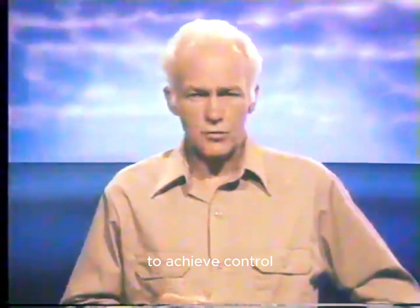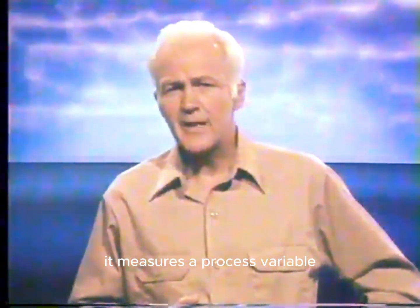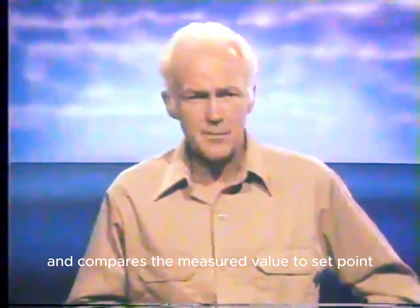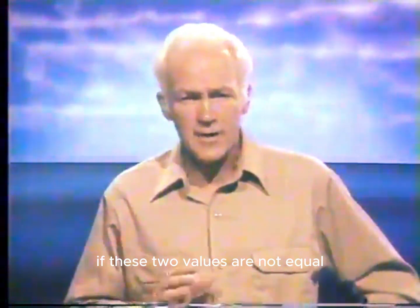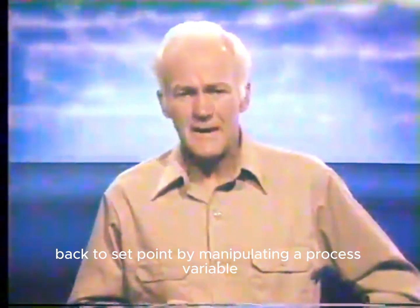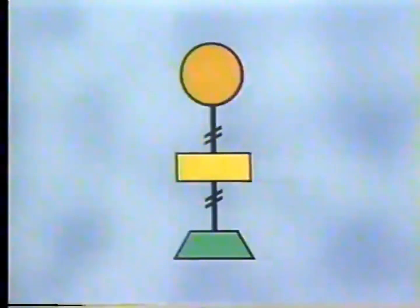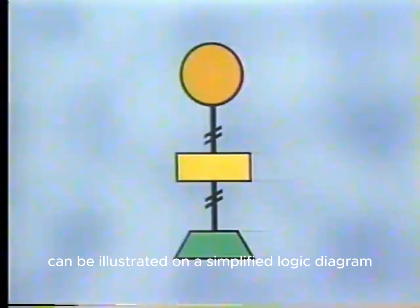To achieve control, a control system performs certain basic functions. It measures a process variable and compares the measured value to set point. If these two values are not equal, the control system responds to bring the measured value back to set point by manipulating a process variable. These functions can be illustrated on a simplified logic diagram.